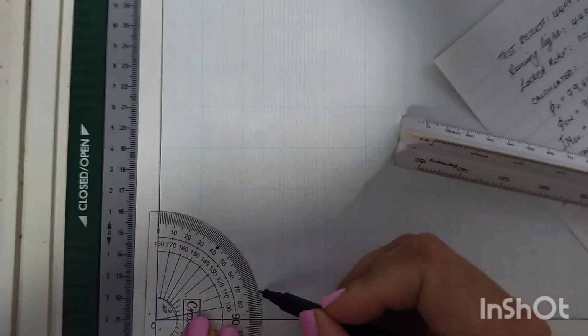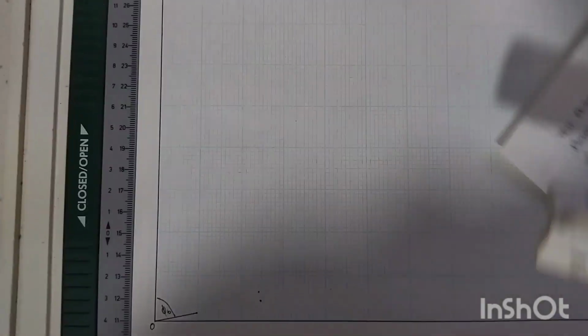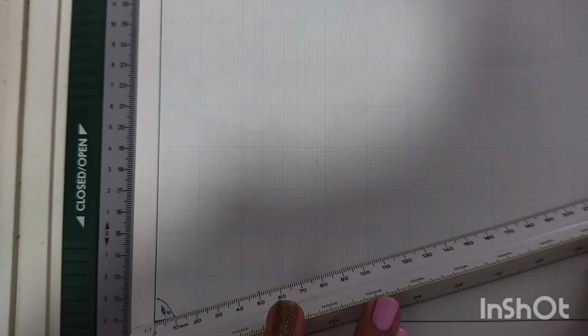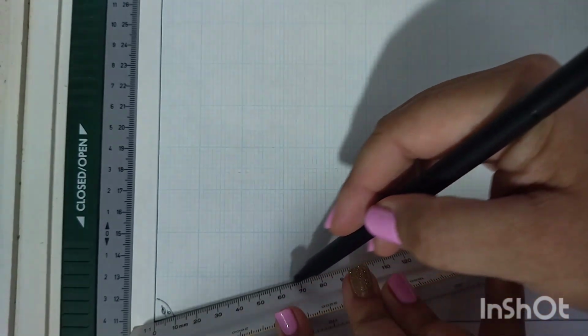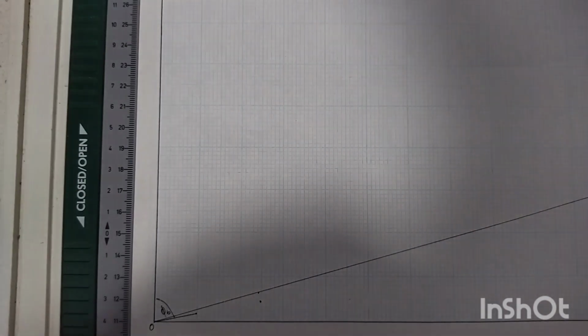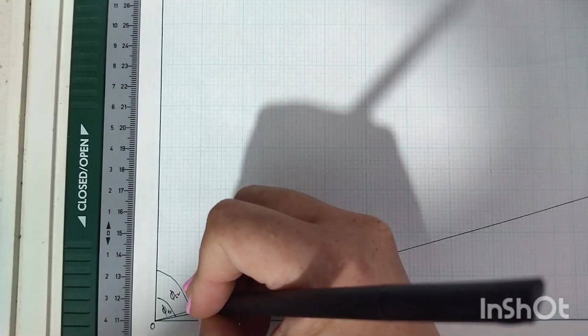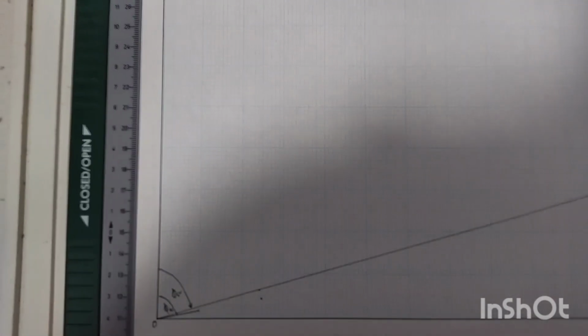Let me just get the right spot over there. And this is 250 amps at a scale of 1 centimeter equals 10 amps. It's going to be 25 centimeters from 0. So, okay, just make sure this fits on over there. Through that point, 25 centimeters over there. Again, this is your short circuit phase angle over there. Now, these are what I refer to as your construction lines.